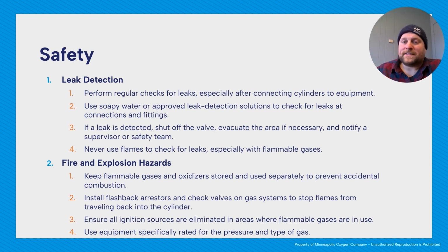The settings for oxygen and acetylene are there for a reason, preventing the drawing of acetone into the system and whatnot. So please, please, please reference them. Plus, they're different for different equipment. So if you're using a Smith, reference their information; Victor, reference their information, that sort of thing. It's not that one size fits all.